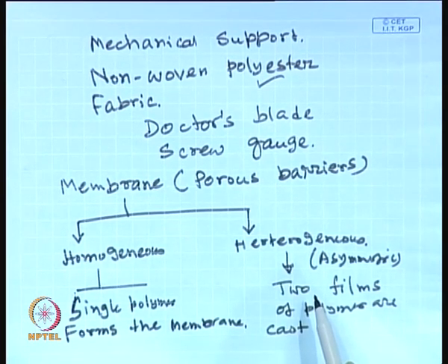The second aspect you are looking for is the quality. So, that is the quantity, and the second aspect is the quality of the permeate, what is the concentration of solute that you expect in a particular species. If it is a case of pollution control, you must be looking for a particular threshold value of a particular species, let us say the concentration should be less than 1 ppm or something like that. If it is a recovery problem, then you must be looking for the concentration of a particular solute in the permeate stream to be above some concentration. So, depending on the situation, the permeate flux or the productivity of the process is very important as far as the practical feasibility of the process is concerned.